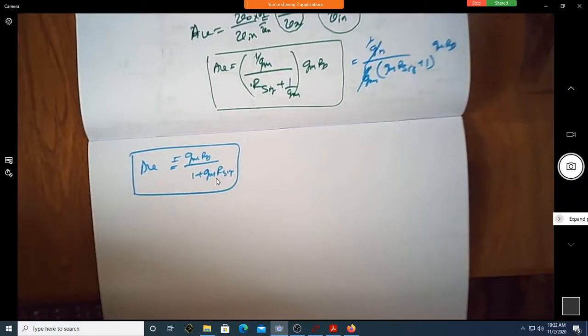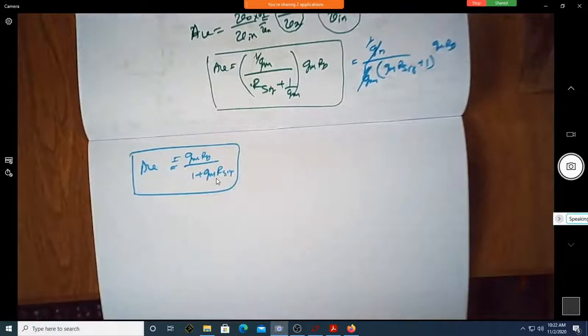What do you mean by R signal being 0? It's an ideal voltage source. Yes sir. For a voltage source, if the resistance is 0, will you call it an ideal voltage source? Yes sir, it is. If there is some source resistance involved with that voltage source, the voltage gain reduces due to the presence of R signal.